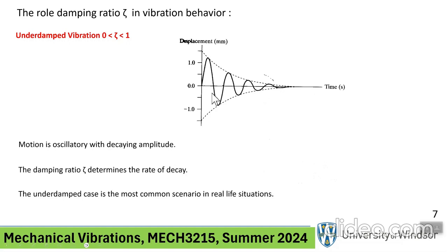Now, this kind of damped system, underdamped, is the most common occurrence in vibration in real life. Okay, let's move on. Suppose the values of C, K, and M give you a damping ratio zeta which is bigger than 1. And if you plotted the response of the mass, which means displacement of the mass as a function of time. Ultimately, that's what you want.